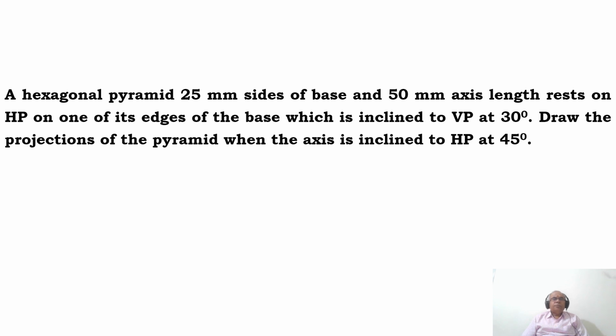Now in this video we are going to take up one more problem on projections of solids, analyzing it and also solving it manually. The problem reads: a hexagonal pyramid of 25 mm sides of base and 50 mm axis length rests on HP on one of its edges of the base, which is inclined to VP at 30 degrees. Draw the projections of the pyramid when the axis is inclined to HP at 45 degrees.